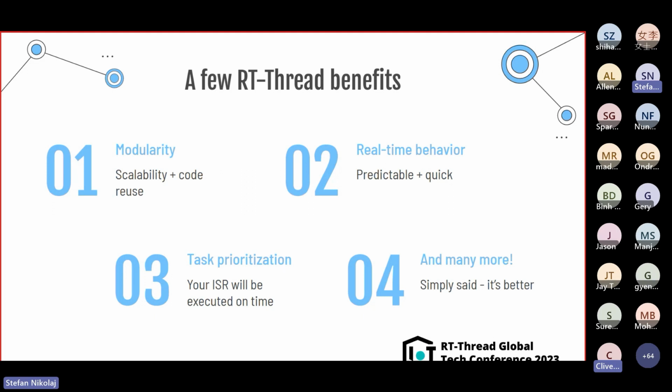Real-time behavior is also a fundamental aspect of a real-time operating system. I mean, it's in the name, and it's precisely this characteristic that makes them well suited for embedded environments. In the context of a PLC, for instance, precise timing is essential for time-critical components. And in the case of a synthesizer, you can actually feel the delay, because the main criticism of desktop computer emulated synthesizers is in the delay. Even a slight delay of 10 to 20 milliseconds can cause significant issues for musicians.